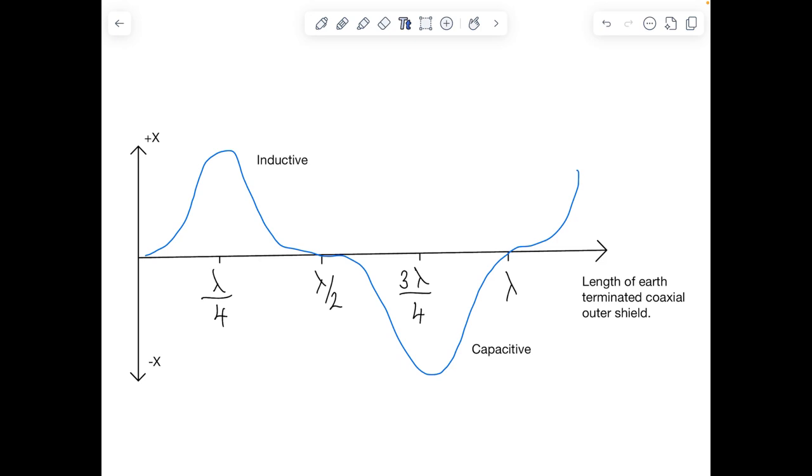And the impedance that it sees depends upon the actual length of the coax cable that is presented. For example, if you apply a noise current very close to the receiver port, which is assumed to be earth, then the impedance will be very low, i.e. near zero.